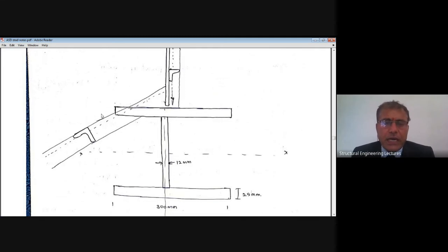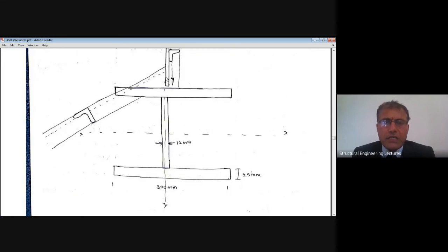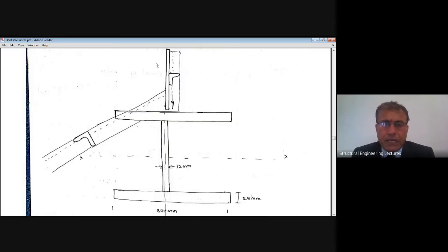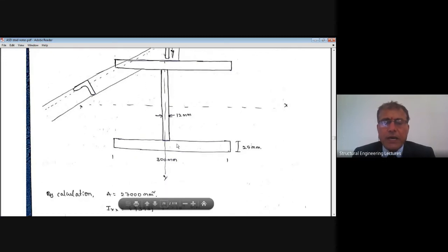Therefore, that is how they are inclined. These are inclined, these are horizontal, right? Same size, ISA 65 by 65 by 6, both, right? And this entire setup of the cylindrical portion along with this hopper bottom is supported on this circular girder. This is a welded plate girder.